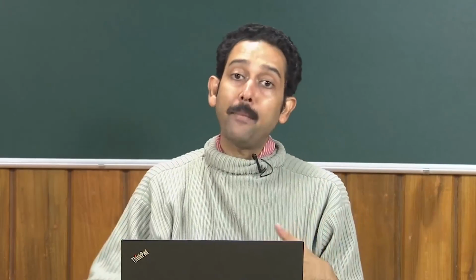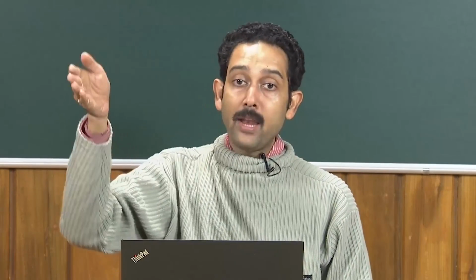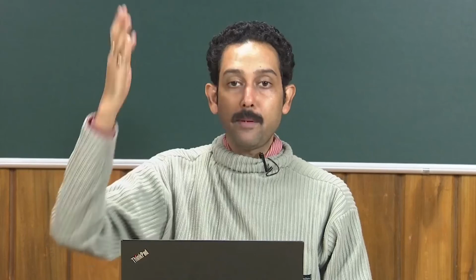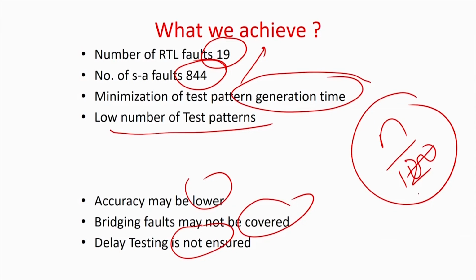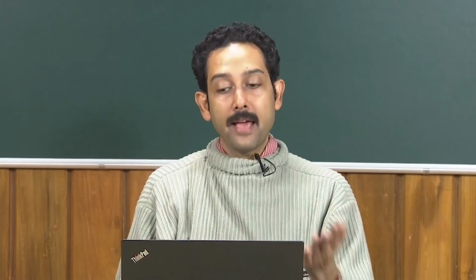But here also, if n is very large, the number of inputs, gates or nets is very high, then again you have to bring down the value of n. There is no other option other than to go for abstraction like RTL and RTL fault models. So even from 2n, we have brought it down to something like n by maybe some tens of thousands. If n is 10 lakhs, at the RTL block level it may be drastically brought down by the bit width, which may be 128 or 256. So the number of test patterns and the test time actually comes down.